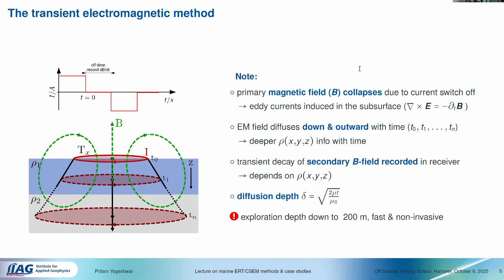Yeah, but high moment won't help you if you use conventional instruments that switch between high moment and low moment, like the Argon system, the high moment recording and low moment recording. But if you really want to go for a really deep investigation, you should use high power dipole sources, and you can still record magnetic fields, but also electric fields. And then you need to go for offsets, like what Mike showed you. For DC, you reach larger investigation depth by increasing the offset between transmitter and receiver. And the same counts here also.